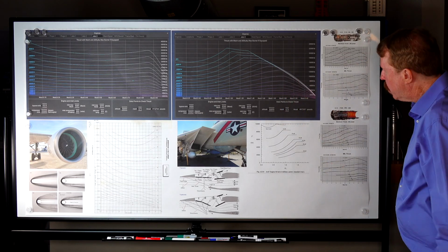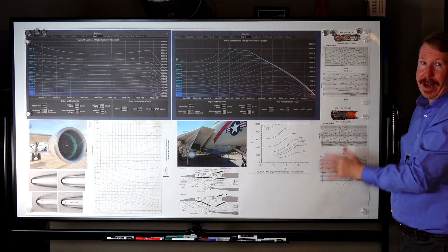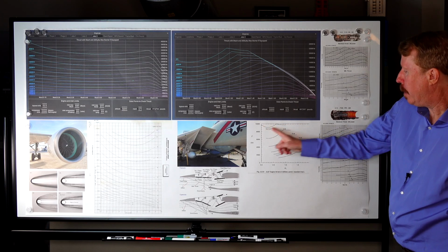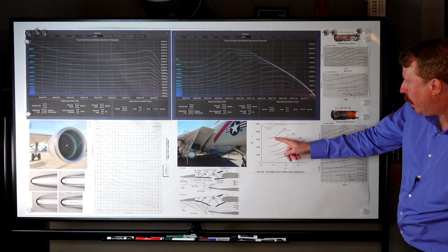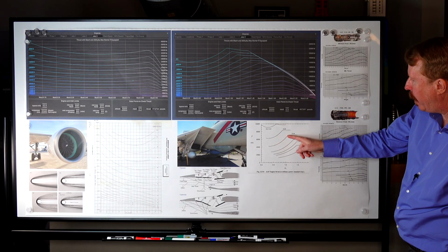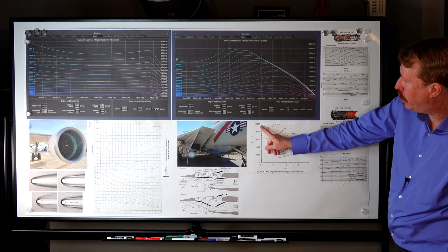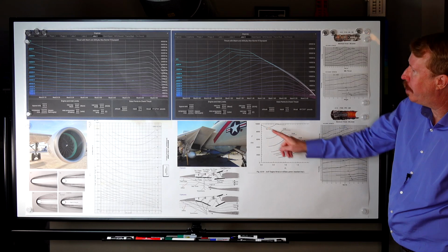for any engine. So why don't we just take a quick look at a few real engines, just so I can compare my theoretical math with real engines. And so what we have here is the curves for a military jet engine, and you can see they just build up, then they hit some sort of a limit, and they level off. And down at sea level, where they can start at 0 speed on the runway, you can even see the speed building up and the thrust degrading.